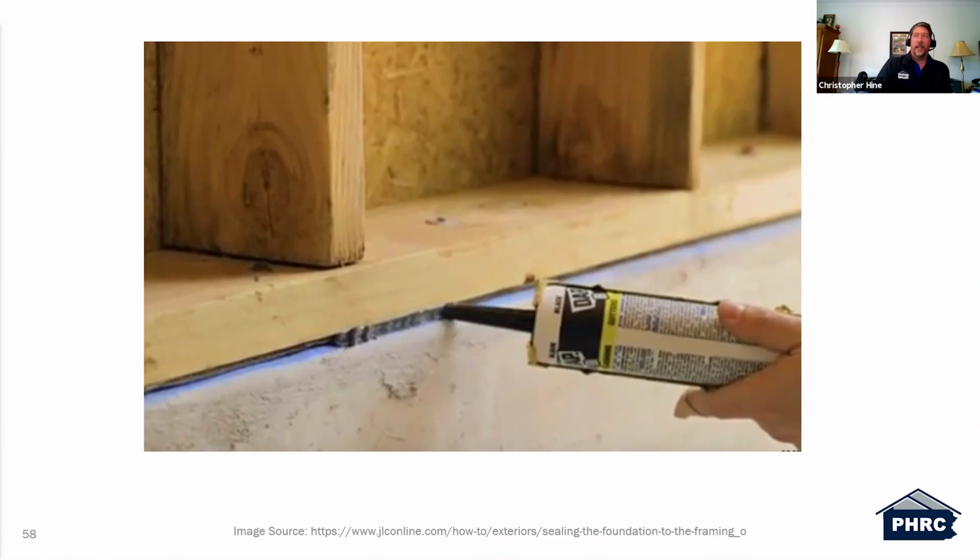So moving on, you know how he did talk about a belt and suspenders approach, right? So he talked about doing some sort of caulking on the inside. If you are using that sill sealer and you want that additional protection of making sure that your air seal is great between that concrete and your sill plate, or the bottom plate of your wall, it's always a great idea to throw in some additional caulk in that gap to ensure a good air seal.